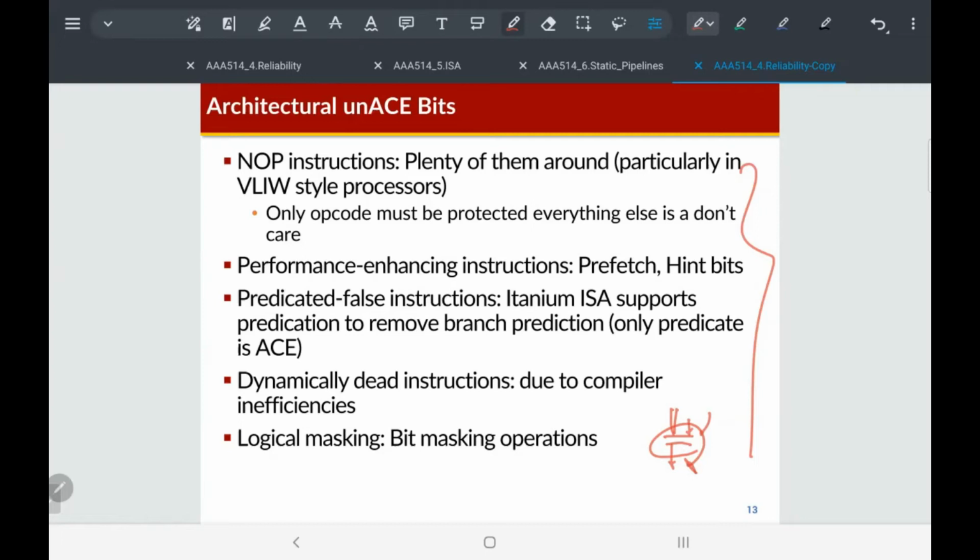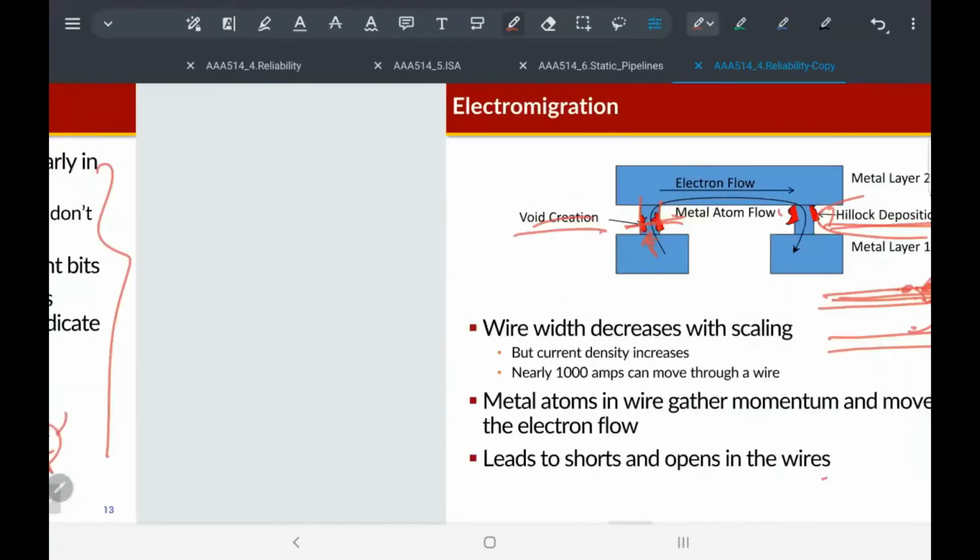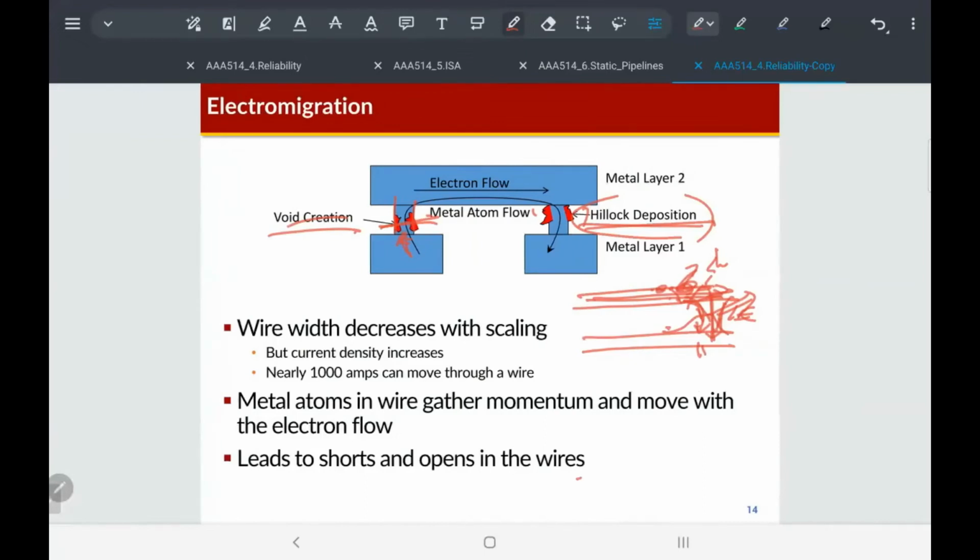So for a QLC device, we can erase only less than 1,000 times, which means that the characteristics of this flash memory cell get worse by erases. Usually the reliability issues are very critical for memory devices because memory devices store a large amount of digital bits inside their components. So we can also focus on these reliability issues because they are getting more critical. Okay.